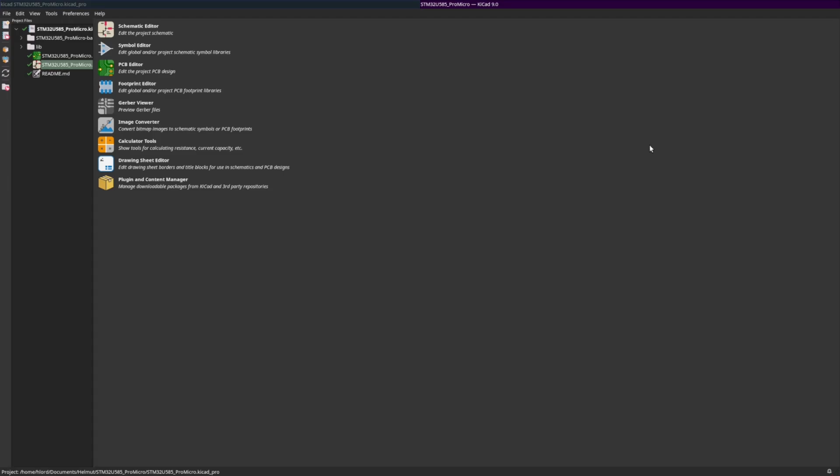In this video, we'll set up ERC and DRC rules, then automate them with a KiCad Jobset, a new feature in KiCad 9. Jobsets, just like the outJob feature in Altium, allow you to export repeatably from your KiCad source files. It prevents the issue you just saw with a flipped QFN making it all the way to production. Unfortunately, not the most expensive mistake I've ever made.